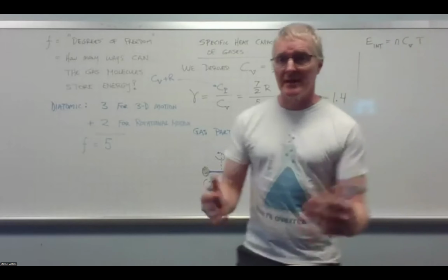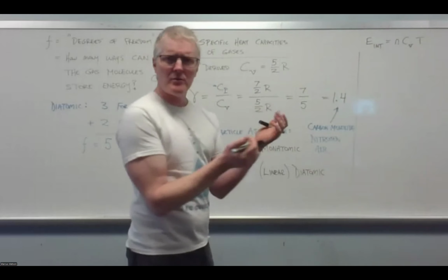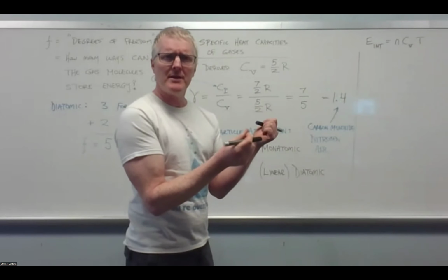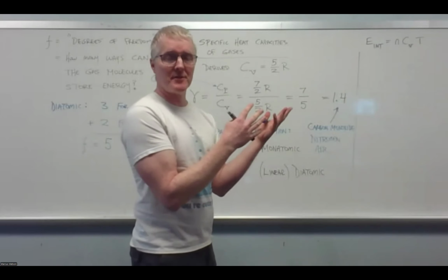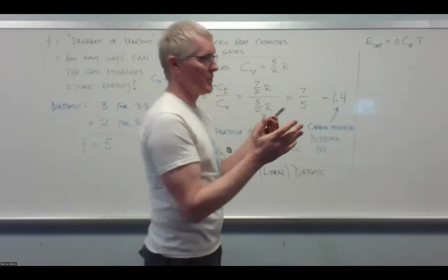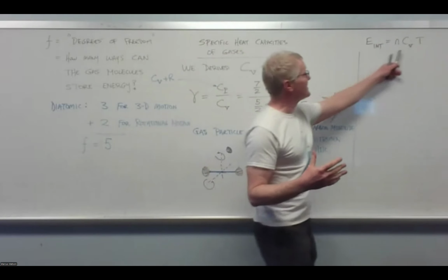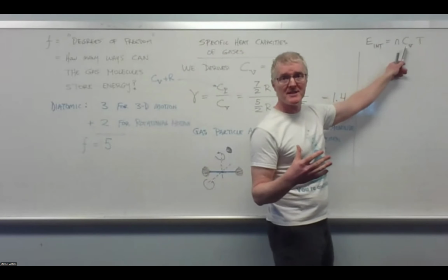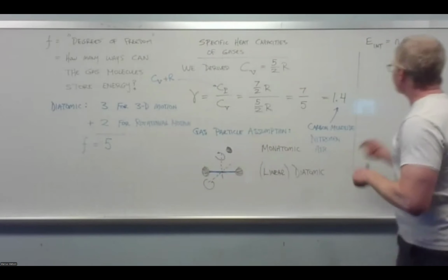Right? That's what the internal energy of an ideal gas is. And I think, didn't we show that last time? I think we did. Well, I had the three halves, right? And in the case of the three halves, we had the three halves R from the ideal gas equation of state. So once we take the three halves R and we generalize, and we say this is what the CV is, this becomes true for ideal gases, okay?